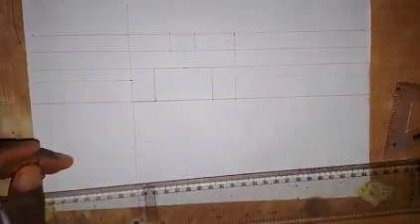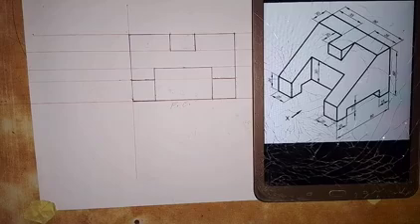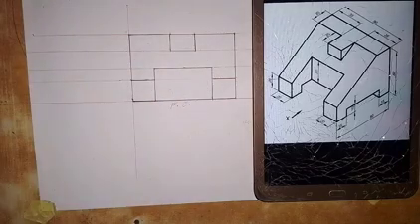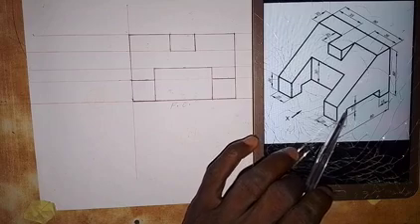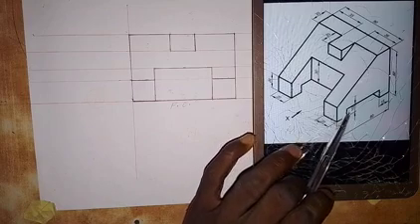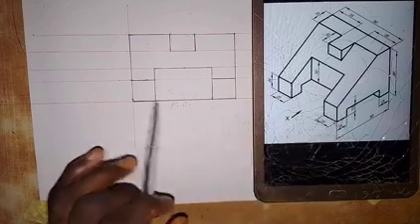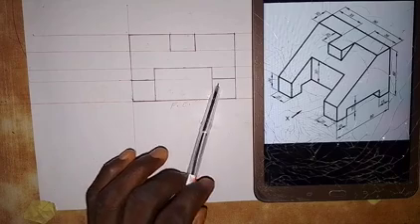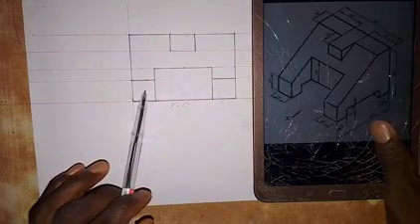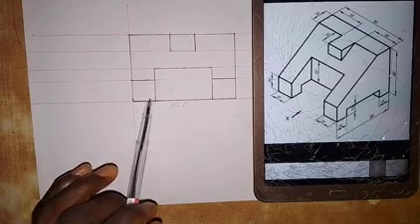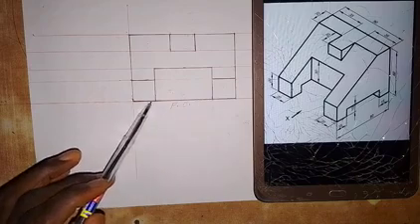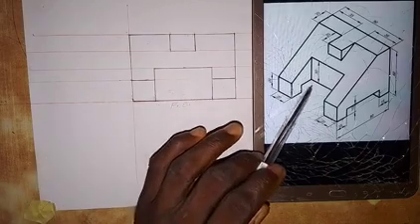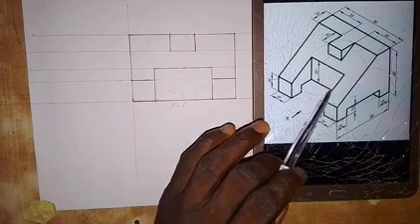I'll pause the video and bring out the shape. I've brought out the shape of the front elevation, but there's something that we need to put here. We have a cut under here, and the distance from here to here is 10 millimeters. So it will be hidden from us in the front elevation for this part and also for this part that we have here. Even this line that we have here is not supposed to be a thick line, because this is at the same level with this.